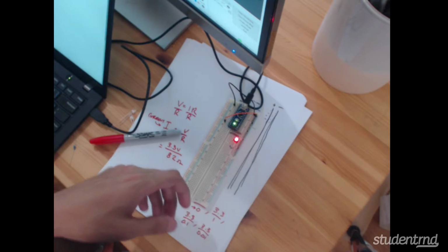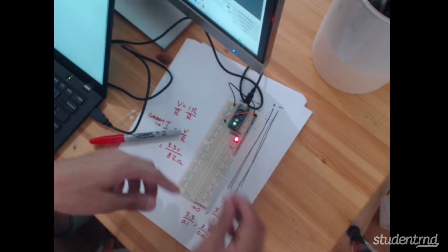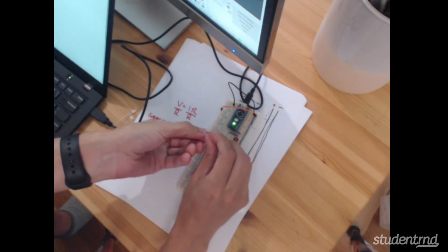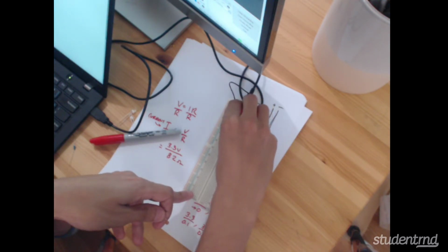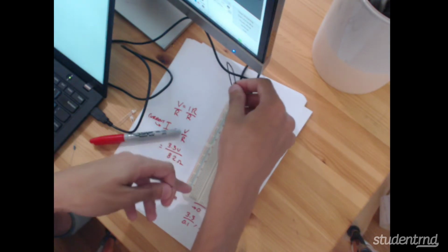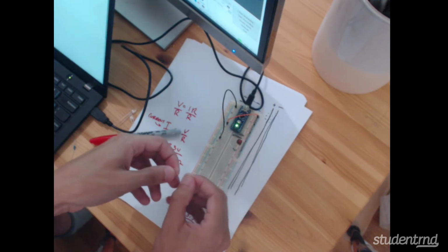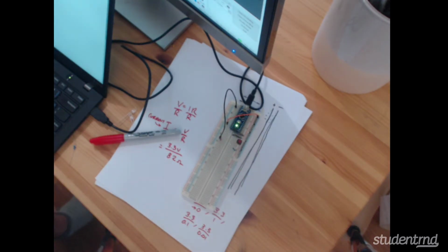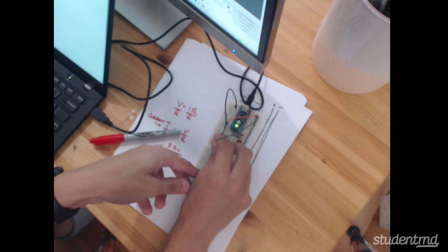So what I can do is I can put this capacitor, and let's find a slightly smaller one that's not polarized. So what I can do is I can put this capacitor here. I'll put the capacitor on this, or this is ground, isn't it? Let's do it on the voltage pin. Let's do this. So we have this voltage right here. This is 3.3 volts. We'll put it down here into one of these rows. And then what we'll do is we'll put this capacitor here. And then we'll take another one of these jumper wires. And we will put this jumper wire up here. And we'll put the other side of the jumper wire down here on this capacitor,